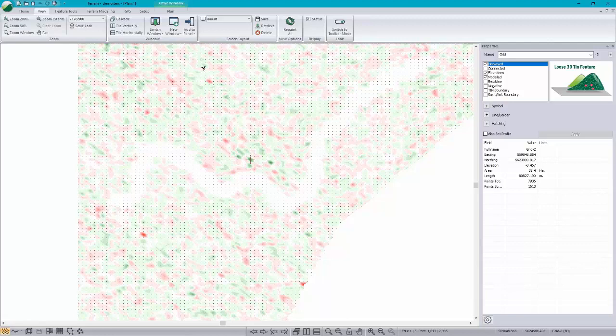In other words, if I start doing road design or some other surface draping operation outside of my corridor, I've got a little bit of error from my original lidar. Not that the lidar was perfect. Lidar has errors built into it, probably around 15 centimeters in elevation. And of course, the points are not infinitely dense, so there are spots that are missed. However, in my corridor, I know that I'm getting as accurate as possible.